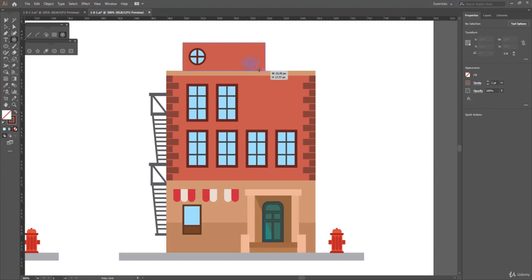Now you see inside of this circle 7 radial dividers and 2 concentric dividers. But the window I want to draw has only 4 concentric dividers and no radial dividers. So I'm still holding the mouse button. I tap the down arrow key 2 times to remove all of the concentric dividers, and then I tap the left arrow key until it remains 4 radial dividers. Then I release the mouse.